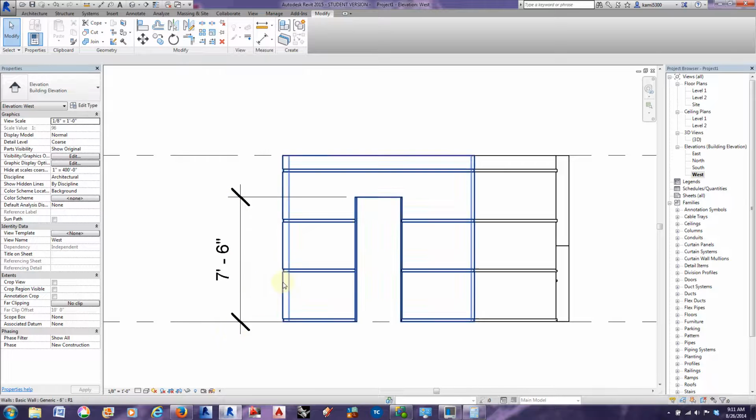And so when you start locking things, walls to other walls, dimensions and things, you sometimes run into problems. You saved it, opened it 2 days later, and you forget that you locked that wall to another wall, and you go to move it and it gives you a constraint, and you have to think back and go, what did I lock it to? And you have to figure that out and then unlock it to move it.